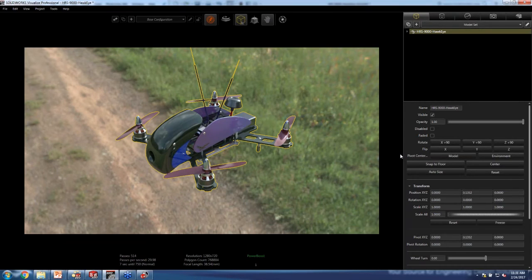So in SOLIDWORKS, you have SOLIDWORKS Motion. By utilizing SOLIDWORKS Motion, you can render out that motion with PhotoView 360, and you can also render that motion out with Visualize. If you have Visualize installed, it puts a little add-in with SOLIDWORKS. You can output it as a Visualize project, and anything you've done in your motion study, gravity, all that stuff, will come into Visualize, and you can render that animation out in photorealism. So again, everything has this symbiotic relationship with each other, and it really is what's the best tool for the current task, not which one you are going to use all the time.